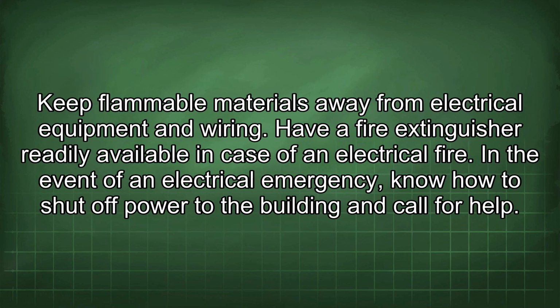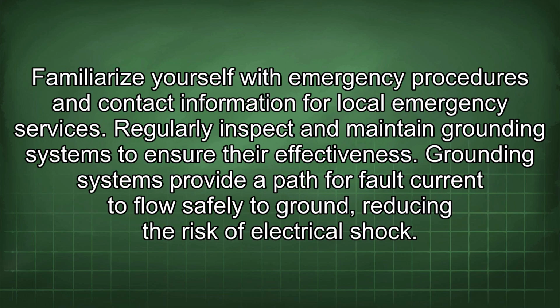Keep flammable materials away from electrical equipment and wiring. Have a fire extinguisher readily available in case of an electrical fire. In the event of an electrical emergency, know how to shut off power to the building and call for help. Familiarize yourself with emergency procedures and contact information for local emergency services.